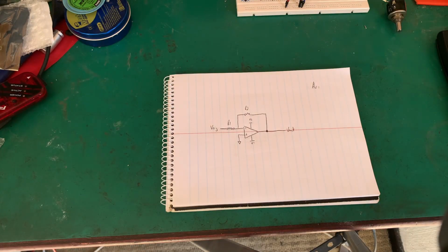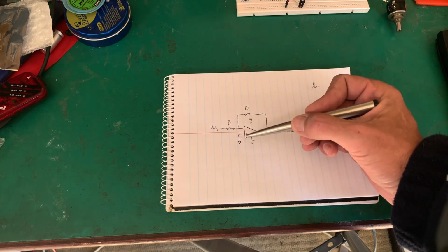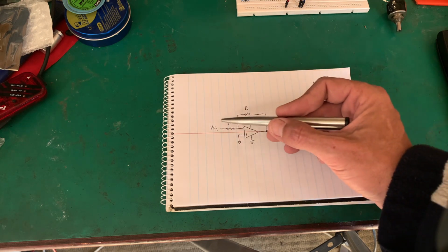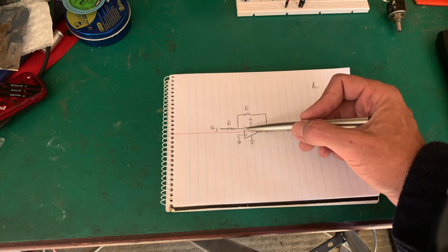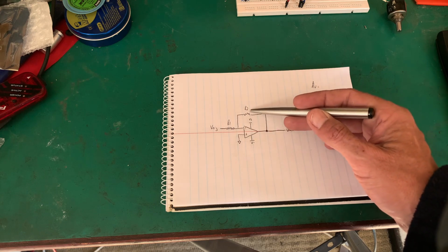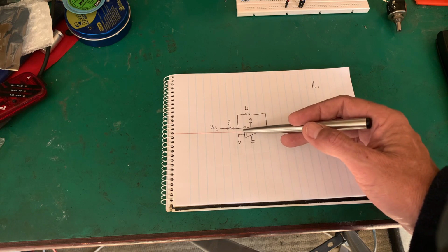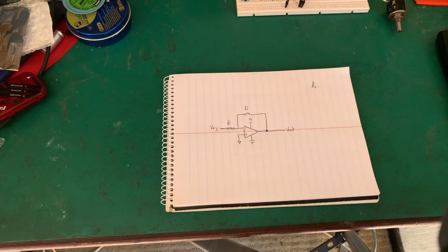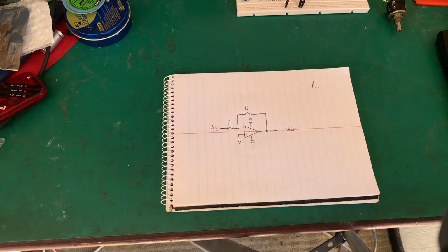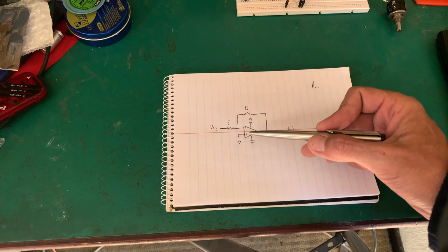Now we're starting to get a bit tricky with our circuit. We have our op-amp. Here we can see the non-inverting input is tied to ground. Our signal comes through a resistor to the inverting input of the op-amp. Output is tied back through R2 back to the inverting input. This looks very tricky. Stay with me, it's really very simple. If we keep our few rules in mind, we can analyze this very quickly.